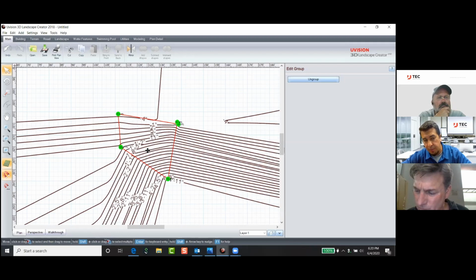Now, the great thing with the U level is you can actually, just like a brake line, and I'm kind of dating myself because I know Jake or Phil probably don't know how to change brake lines, but just like you would bleed out a brake line, you can bleed out the U level and basically get rid of those air bubbles. That little square package that says U, that has the big U on the U level that Paddy showed at the beginning, is actually an oil reservoir.